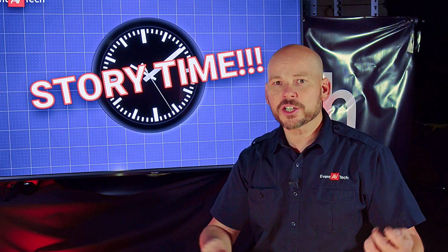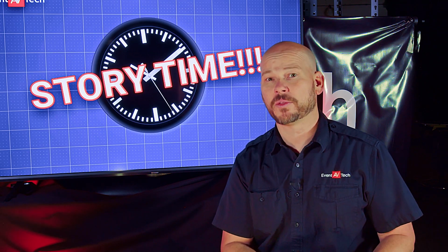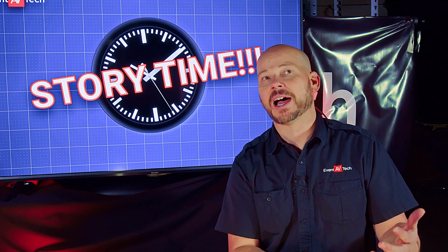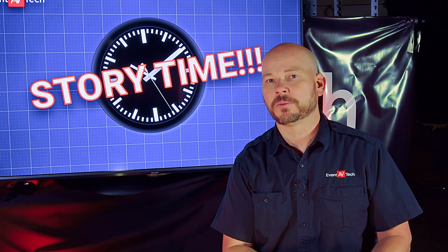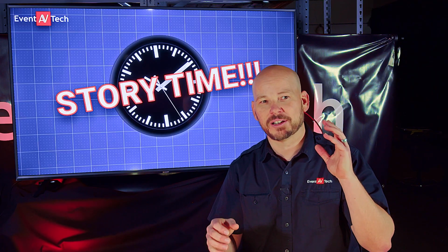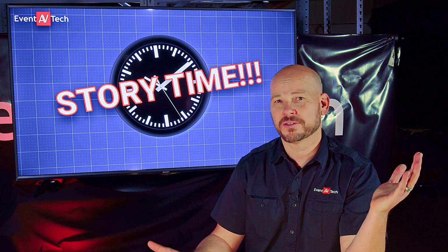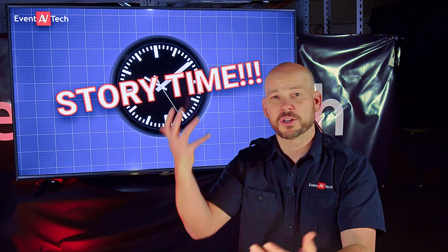So I had to show them, okay, we've got to go back to the beginning. We've got to go back to where the problem starts. So if the problem starts with speaker 5 out of 30 speakers, then let's deal with speaker 5. Let's not go to the end. Well, sure enough, we went to speaker 5. There was a bad Phoenix connection. The wires were out, and we just plugged it back in, and all of a sudden everything started working. Yeah, I mean, that particular job, because of the size of the system, it was days of troubleshooting distributed audio systems.